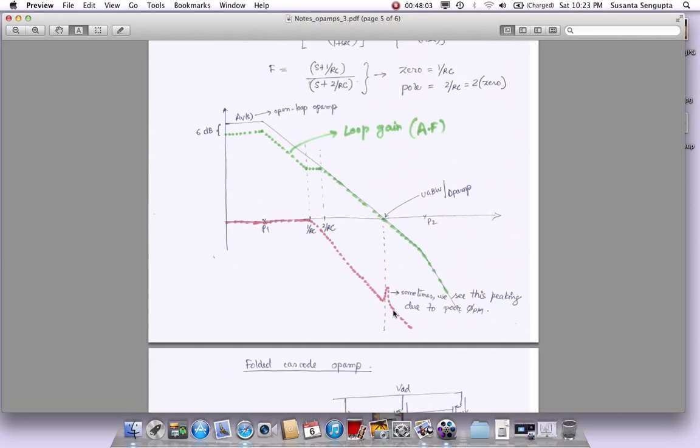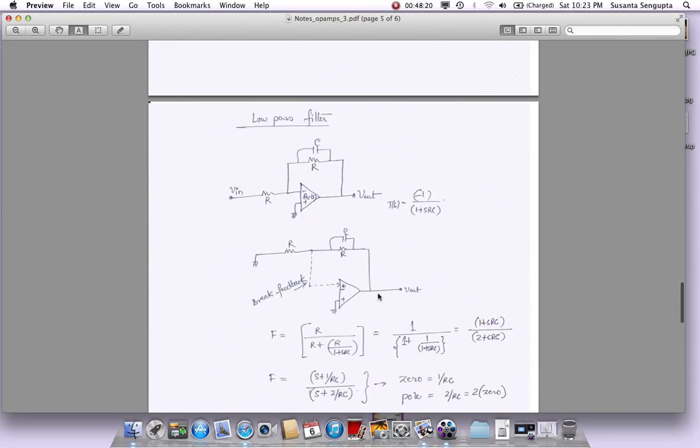There a peaking happens. So first of all, it could happen because of the phase margin. If your phase margin is not good, then you might start seeing more and more peaking. The second point is, can you live with this peaking? Well, if you didn't care about this far out rejection from this filter. When you make a filter, you're trying to filter something out. What are you trying to filter?